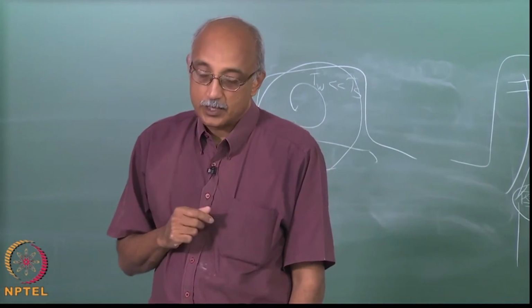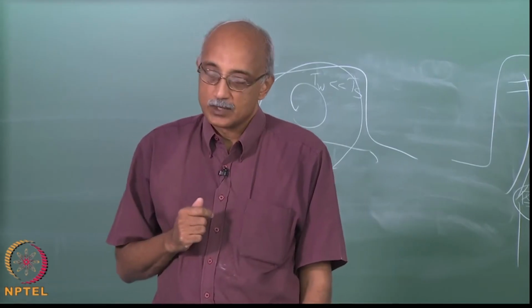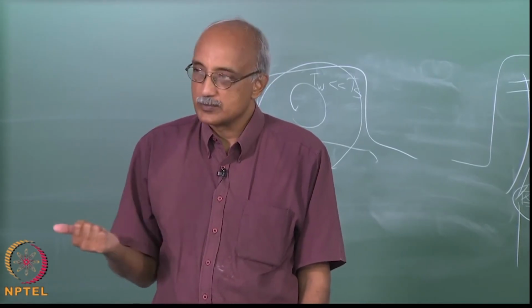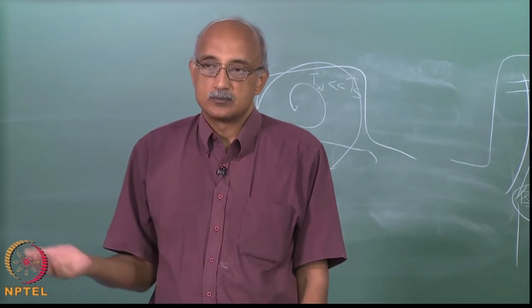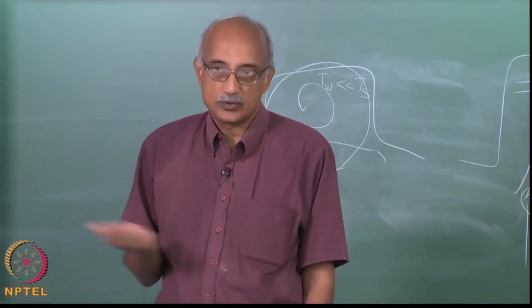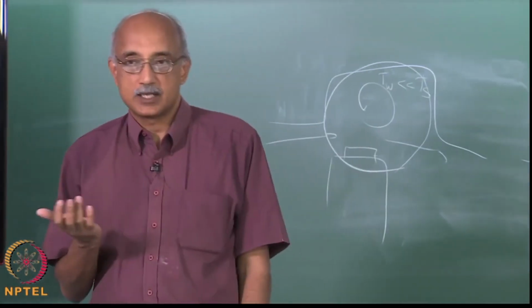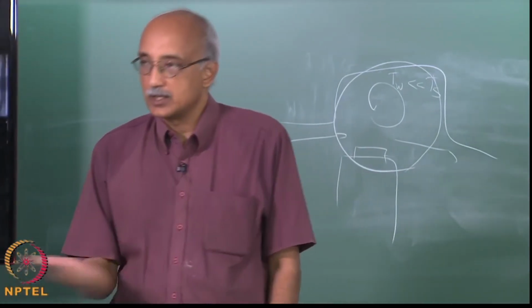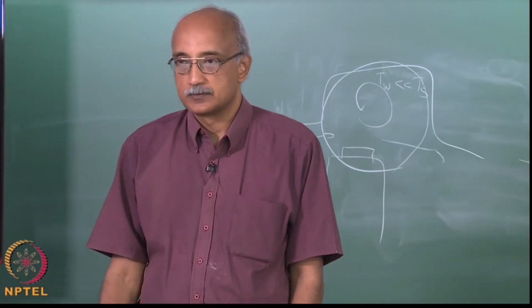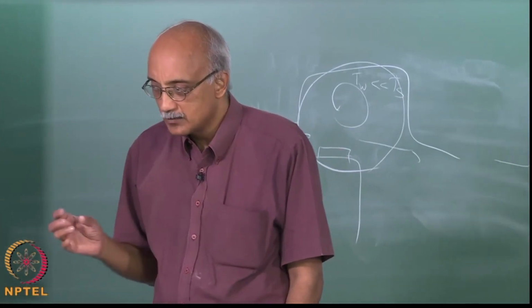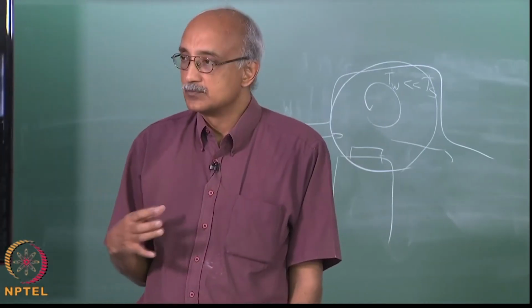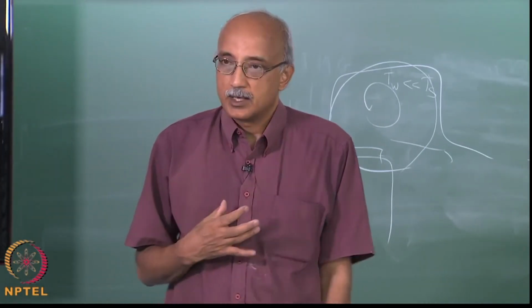surface. Now, the disadvantages, as I mentioned before, the investment cost to first set up the CVD reactor is significantly more expensive than virtually any other type of system you can imagine, particularly for doing something like a coating on a surface. The second problem, CVD films are not particularly well adhered to the substrate, and the reason for that